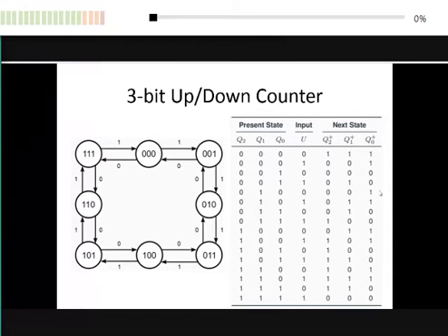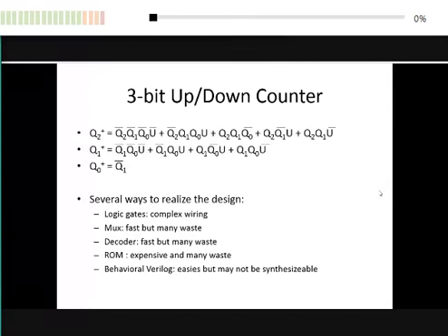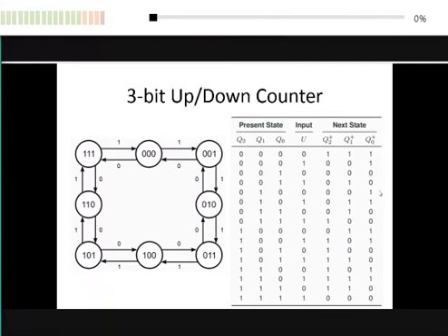Scientists think, how can we reduce this complexity of the next state? Okay, you can try repeat this example by trying to change from D flip-flop to JK or T flip-flop. You will see something surprising. Okay, look at the excitation table on last week notes. So replace the next state value. If JK, your next state should have two groups.